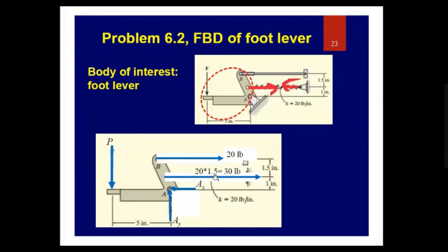So I have to show the numerical value, and then there is also some force at B, and this force is given in the question. It is equal to 20 pounds, and this is a link, and I have told you that whenever you are removing a link, the reaction force in a link is always along the axis of the member. So show a force along the axis of the member.